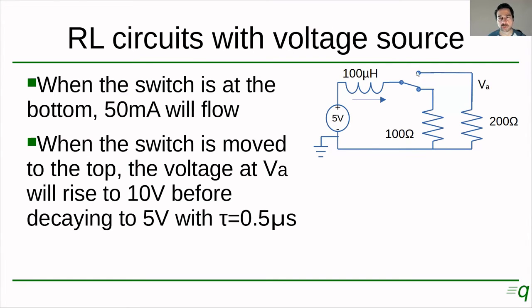When the switch is moved to the top, okay, these 50 milliamps will keep flowing through the inductor, but this time through the 200 ohm resistor.